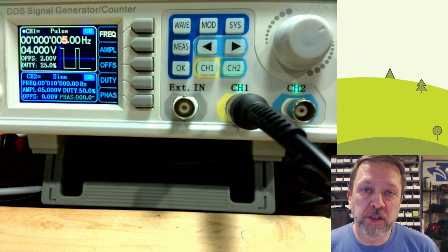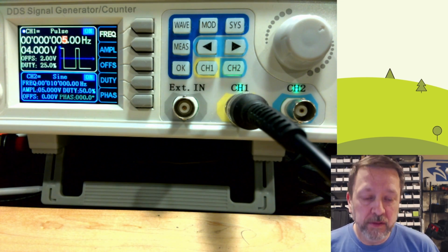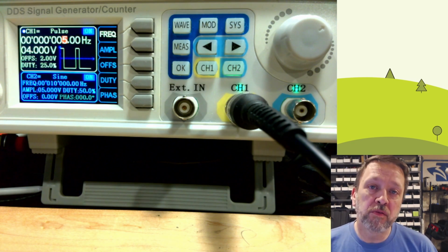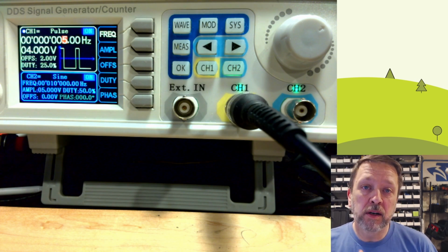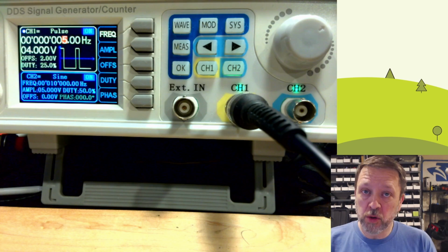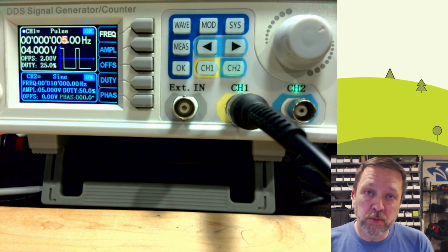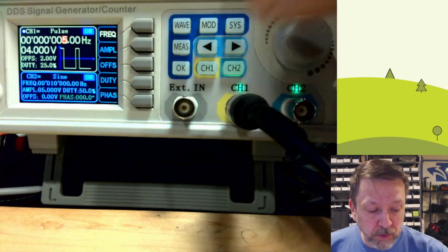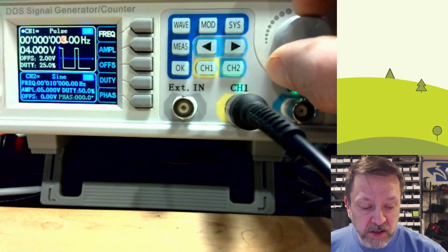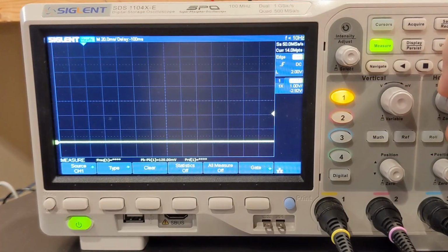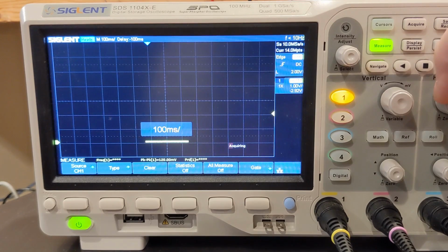Let's say we wanted to do a test of a button click, effectively an interrupt, once every 5 seconds. And we want to test both falling and rising. So we have a falling edge, 5-second pause, then a rising edge. So our total wavelength is that fall plus rise. 5 plus 5 is 10. So that is our period. So the frequency is the division of that, or 1 over 10. So we could adjust this to 1/10.